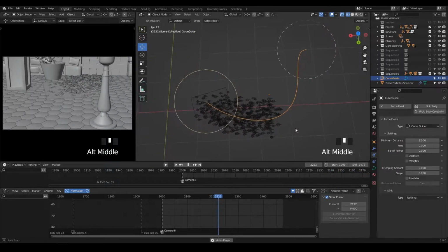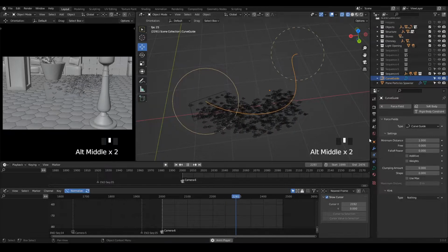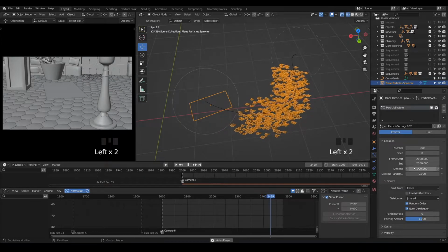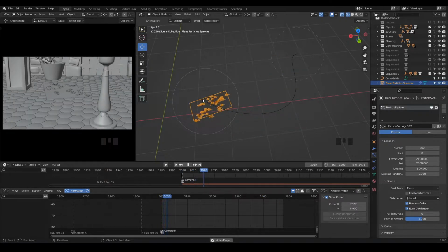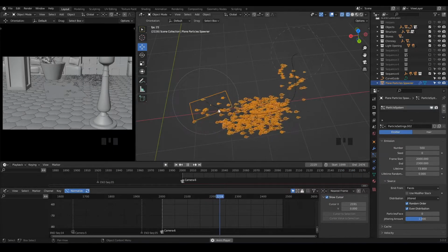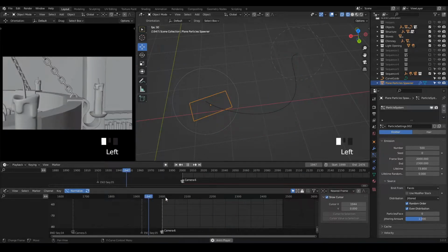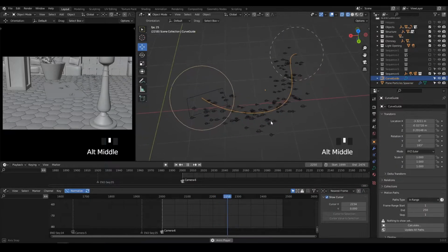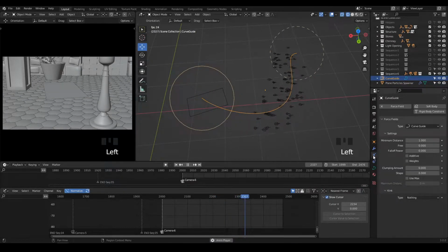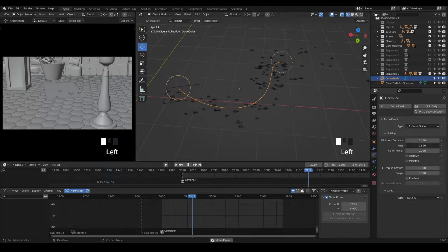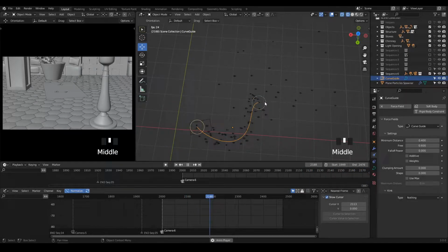The speed of the particles depends on their life, so the longer they live, the slower they will go from one end to the other. If I reduce their lifetime, let's say to 60, see, the ones that are spawning are a bit faster. And you can see that once they arrive at the end, they all die. Okay? And now, in the settings of the curves, you've got 3. This is a few frames, after which the particles at the end are free.